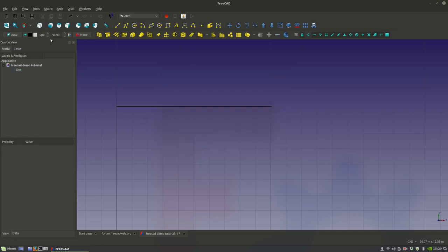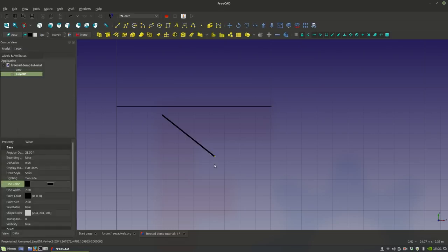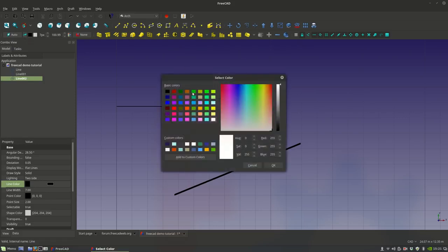And also, if you see here, these tools here are the general tools for any object that you apply it with. For example, the thickness of the line is already one, and the opacity, this is the font size of the object, and then this is the color of the object. So if I were to change this to maybe 3 and 4, you will see that any line that I draw here by default is going to have these properties, as you can see here.